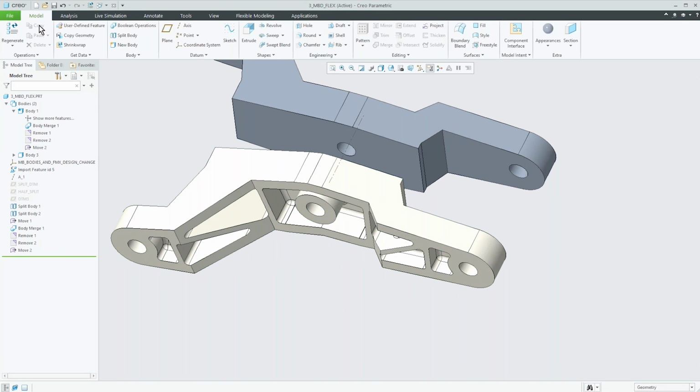Now, something that I haven't used yet, as we looked under this body menu, we have the Boolean operation. We've been adding and subtracting things, and splitting things, obviously. Now I'm going to create a new body. An empty body. Before, when I'd create some geometry, I'd say make it into a new body. But in this case, I'm just going to create an empty file. Let's give it a different name. We'll call it a wheel. Now we have that new body, and we can see that he's the active one by the little indicator here. Now I want to start creating some geometry for him because he's empty right now.